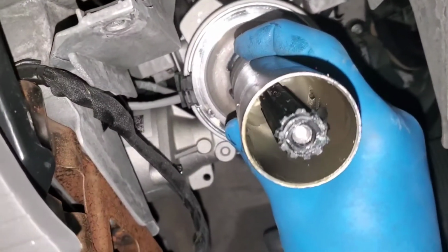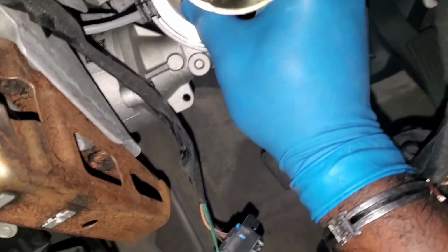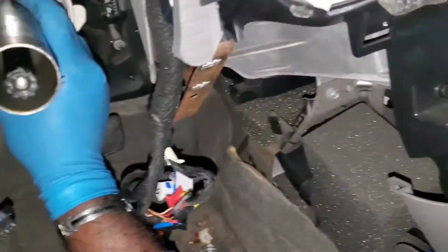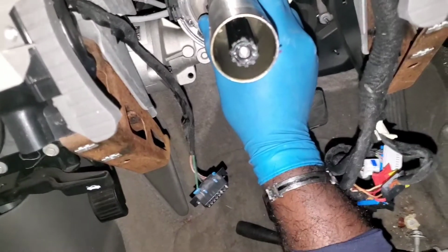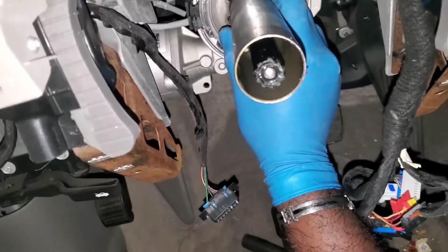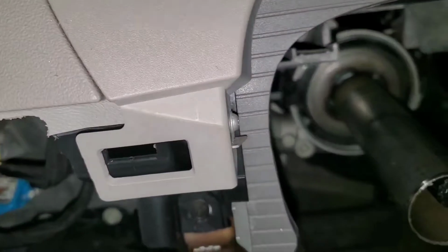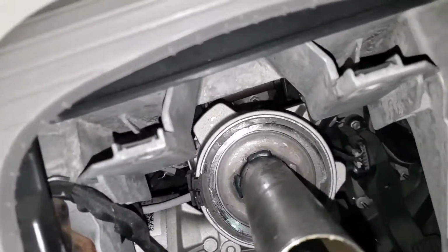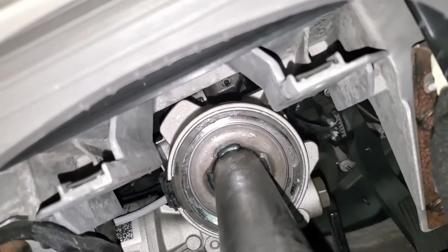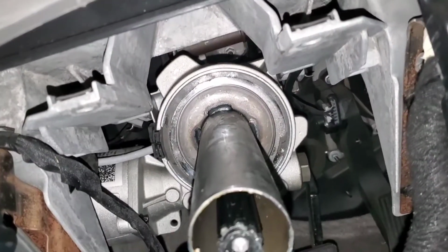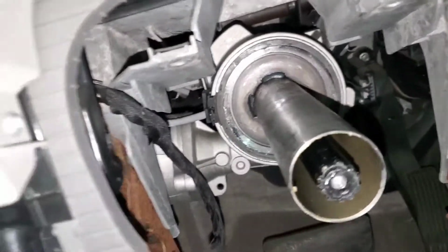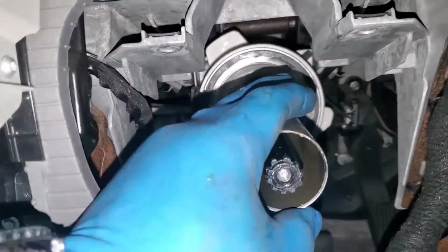Luckily, this doesn't seem to have any sort of indexing, so as long as it's flush, the snap ring will lock in behind it. All right, need two hands again. Here we go. If there's a pro tip I can give anybody, get the biggest snap ring pliers you can get, and double up on the safety glasses. But anyway, that's in there.